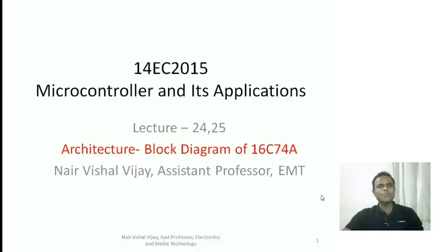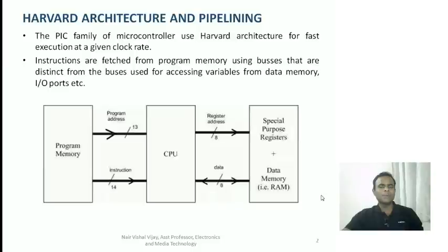Basically your PIC microcontrollers are based upon an architecture called Harvard architecture. Now, a Harvard architecture means your microcontroller accesses your program and data from two separate memories called program memory and data memory. And it also has distinct buses for doing that.